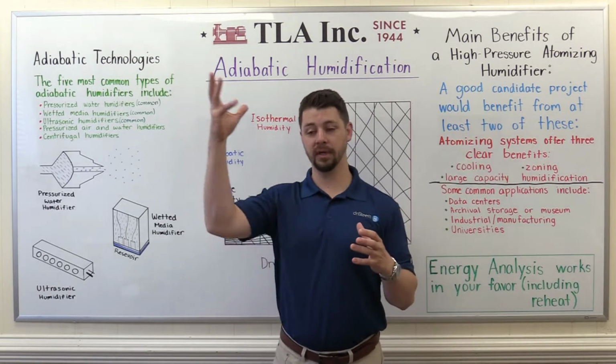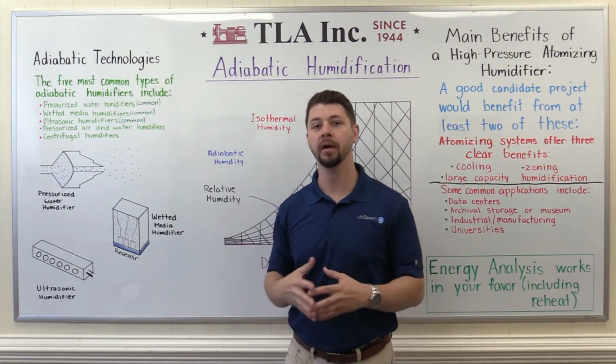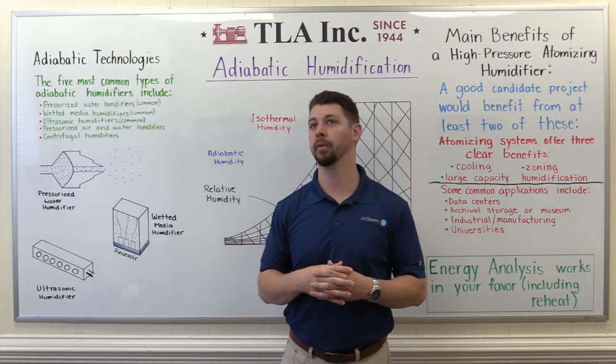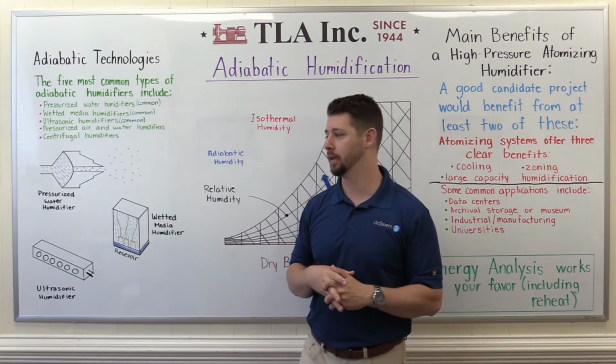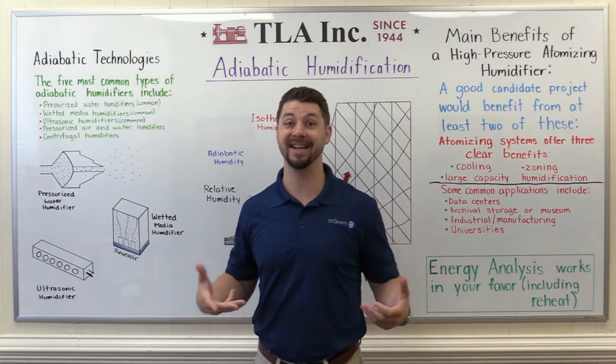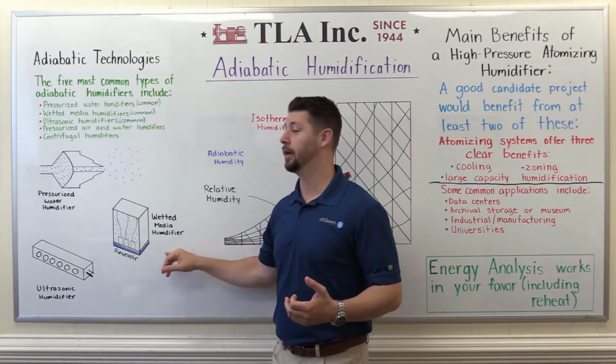This is wetted media, where you cascade water over the top of the media. Now, the good thing with these is they're really energy efficient but require really constant loading, because this is a big wet sock. And what do big wet socks do? They stay wet. So large varying loads don't fare well with wetted media.